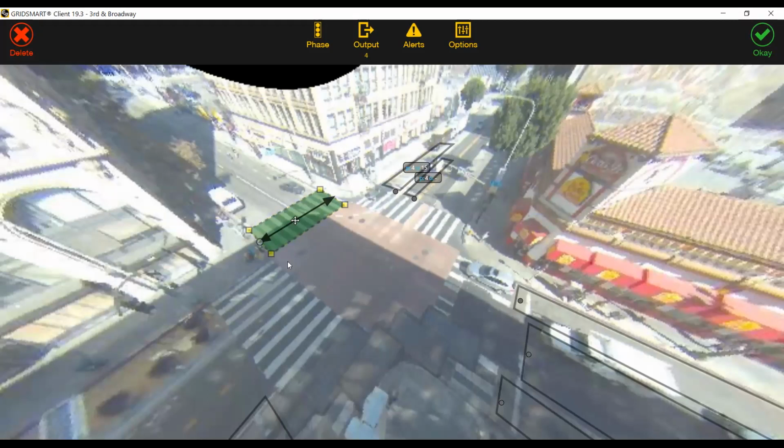There's lots of example use cases in the field. You can use these at hot crossings to extend reds or hold reds. There's a number of ways that these can be utilized, but in this particular case, this would be a very standard use case for that PED zone.